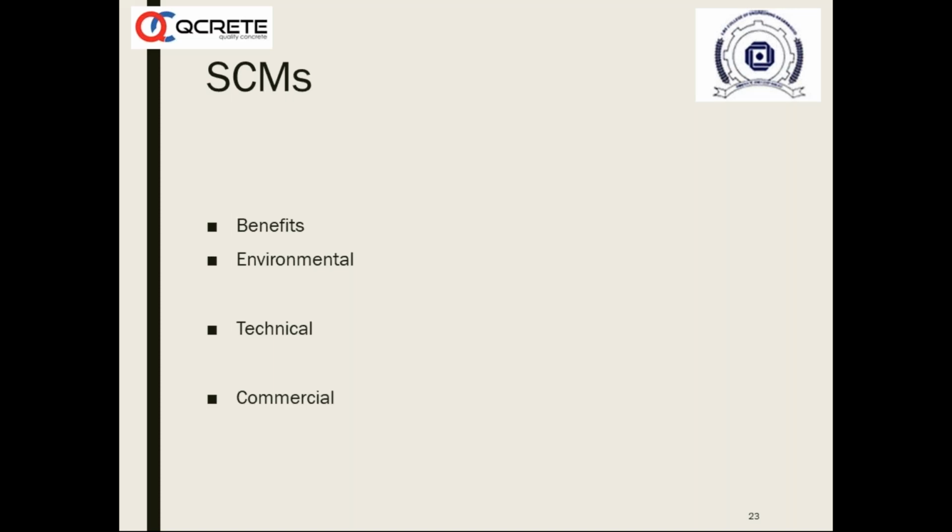Only when they are used in the presence of cement and water do they react and participate in what is called a secondary hydration process, bringing more stable, denser compounds into the body, and hence it gives a durable structure to the concrete.